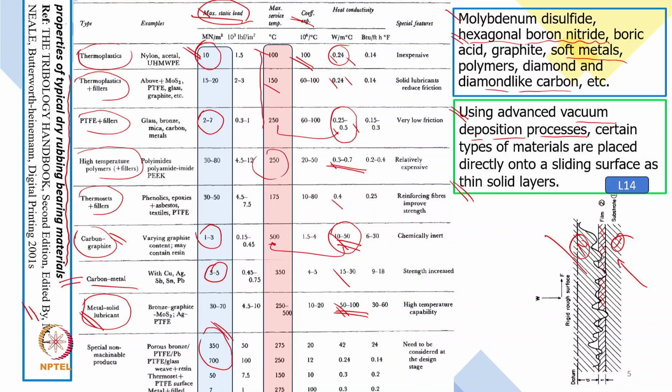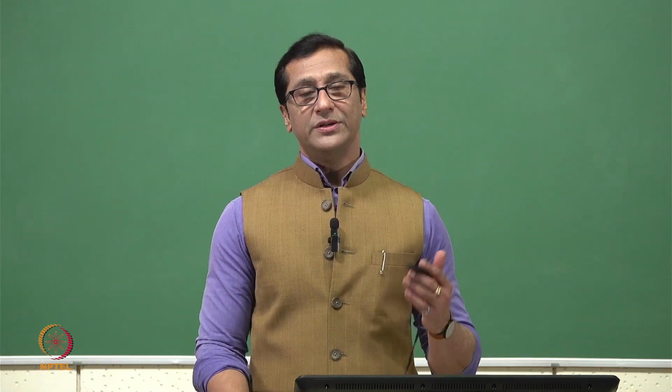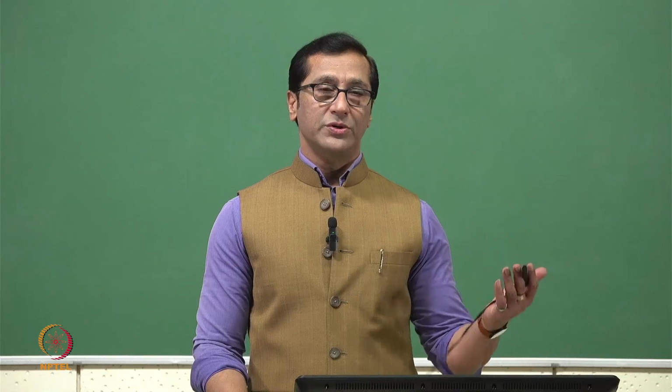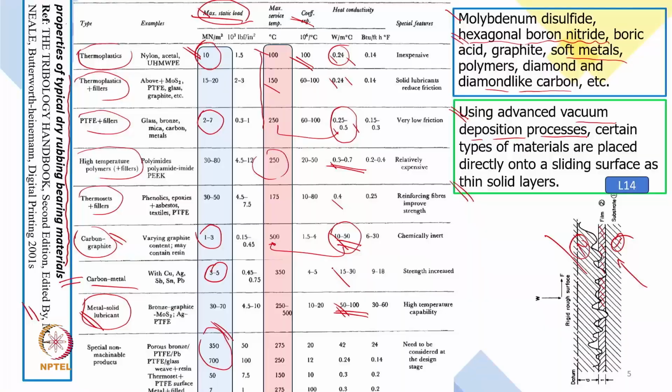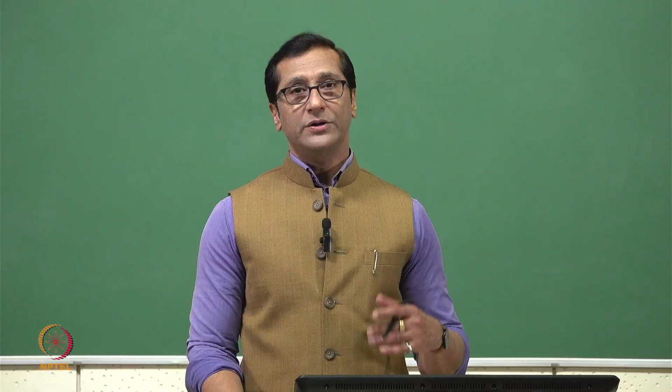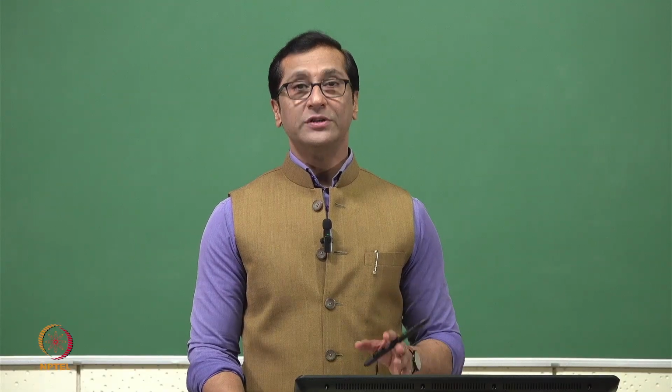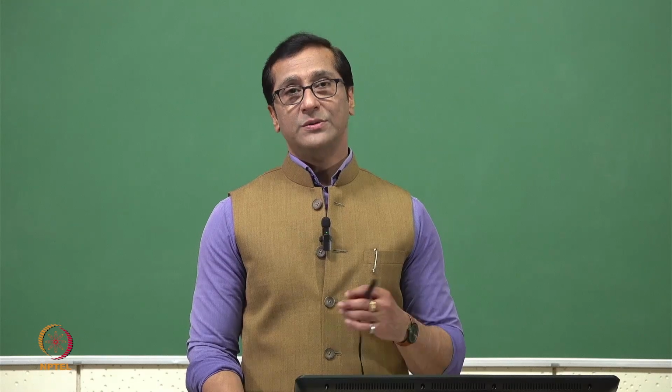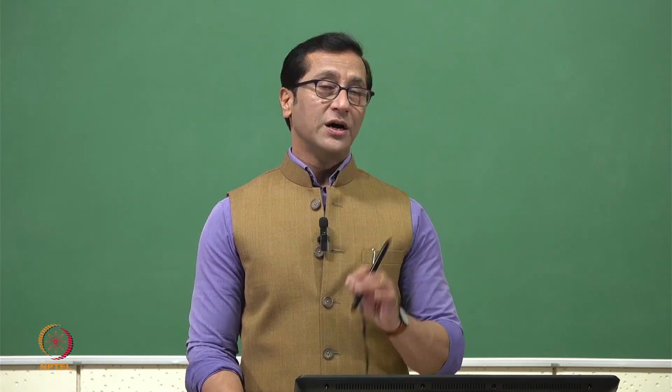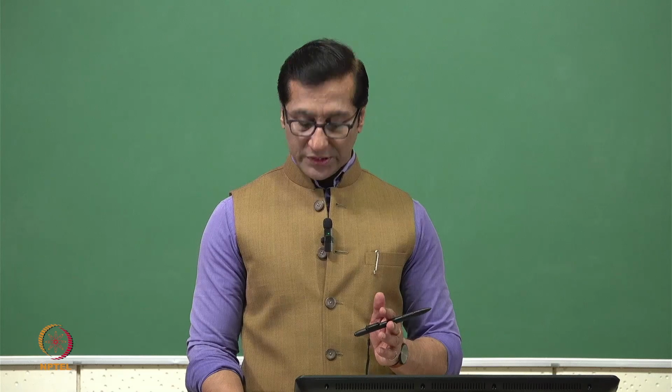So that's what I say: whenever you are going with a material and you say now above 100, above 150, above 200, above 300, materials need to be changed according to that. If thermal conductivity is on the higher side, the permissible maximum temperature will also be on the higher side. That is what we really keep in mind. Now these data are available in literature; only the interpretation, inference and utilization of those data are important. How do we utilize them for the maximum benefit for our purpose?